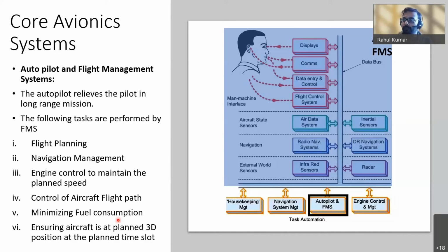And when it approaches the destination, the aircraft is lighter. If the aircraft is light in weight, it needs less fuel while landing, right? That is controlled by your FMS. It will keep on tracking the weight of the aircraft and accordingly adjust the fuel consumption, right? Obviously that will make the aircraft more efficient.